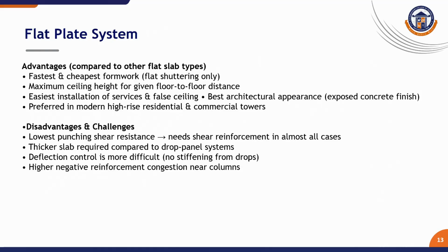Some disadvantages or challenges are: lowest punching shear resistance, almost always needs shear reinforcement, thicker slab required compared to the drop panel system, deflection control is more difficult, and higher negative reinforcement with congestion near the columns.